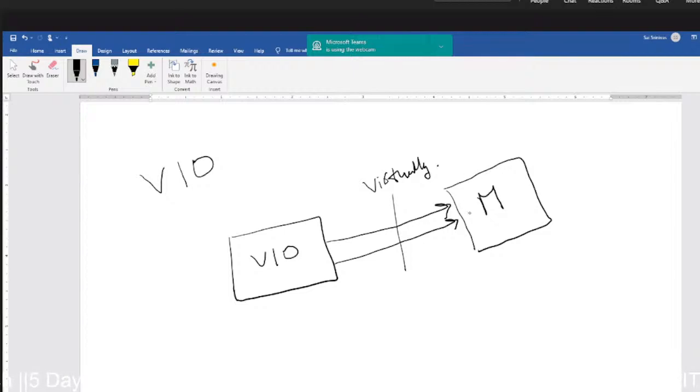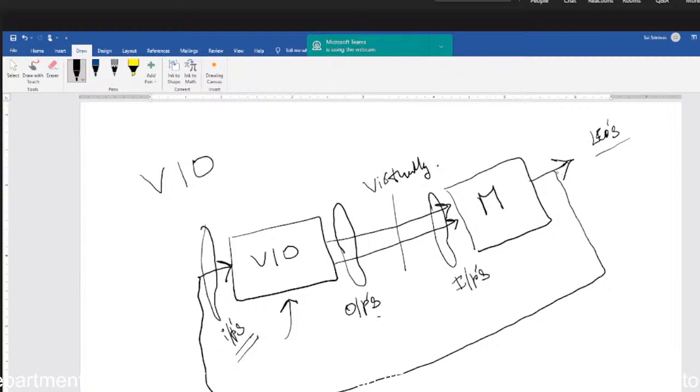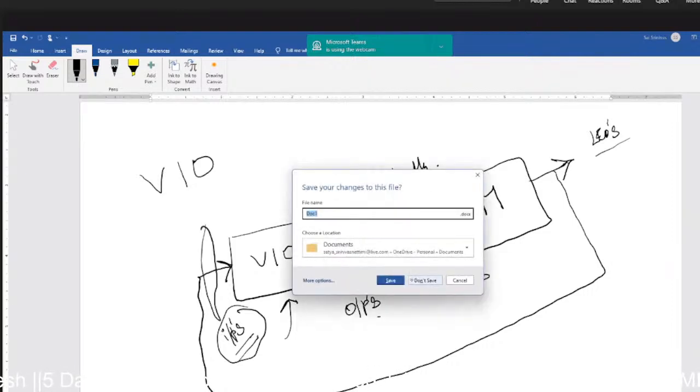So this is a module, right? To this module we have inputs. These inputs, instead of connecting to slide switches physically present on the FPGA development board, we are using a VIO to provide these inputs virtually. And the outputs of the module are connected to the virtual inputs of the VIO. So this bypasses the physical connections or mandatory connections that you would be doing via the onboard slide switches or the LEDs. So this is the concept.